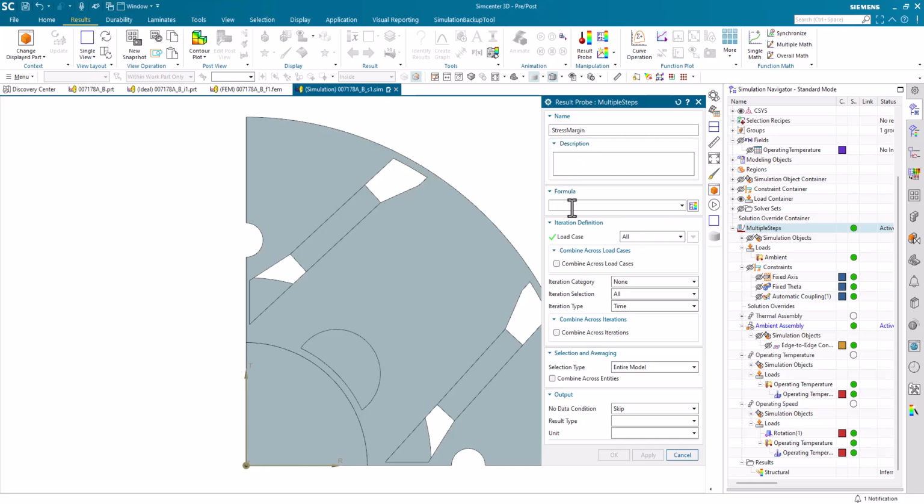It's going to be based on stress. So I'm going to say 1 minus a ratio of stress. So I had stress VM, divide that by a yield function. We have an out-of-the-box function called yield. Yield will evaluate an element's material, and it'll look for the yield strength of that material. And if it's temperature dependent, it'll use the temperature dependent value for a given node, its temperature, and that element. Go find me the yield strength of that material at that temperature. So it's a basic stress margin here.